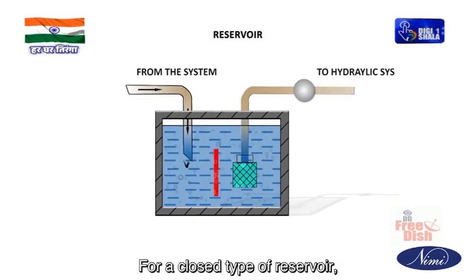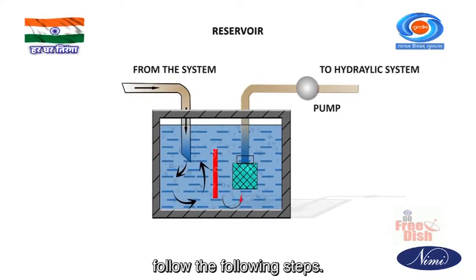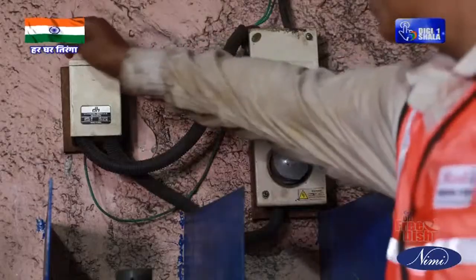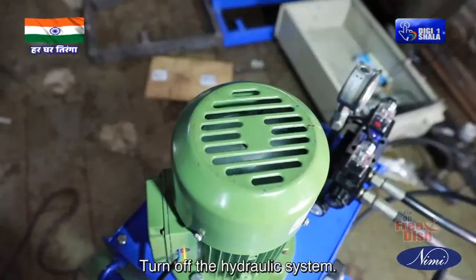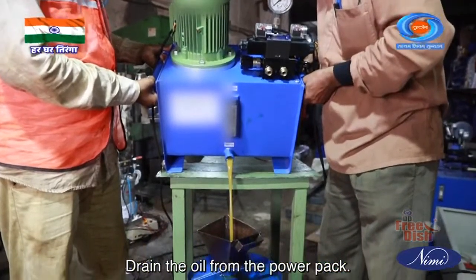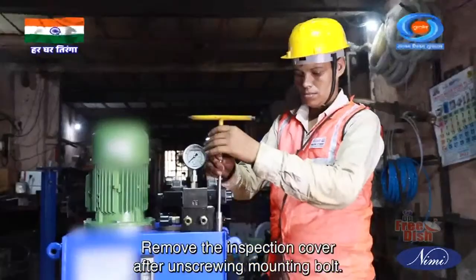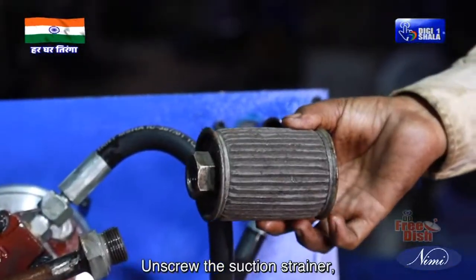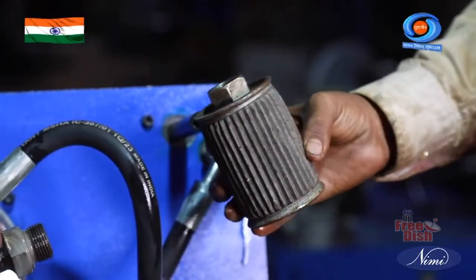For a closed type of reservoir, follow the following steps. Turn off the hydraulic system. Drain the oil from the power pack. Remove the inspection cover after unscrewing the mounting bolts. Unscrew the suction strainer.